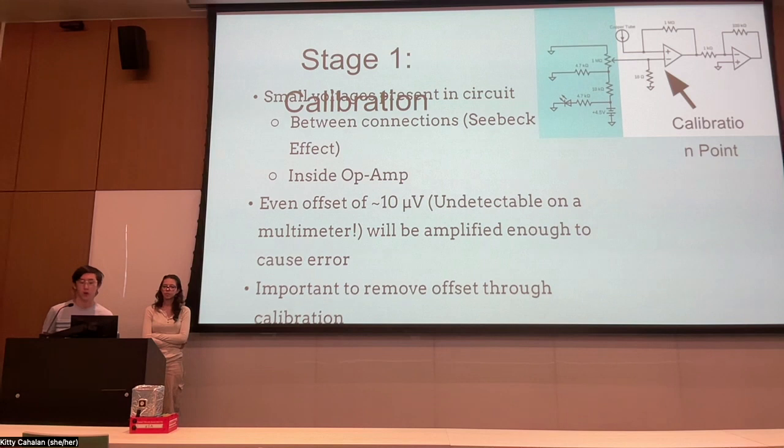The calibration circuit is powered by a 4.5 volt battery, and through this resistor network it allows us to feed anywhere from 0 to 10 millivolts in order to cancel out any offset of that circuit.